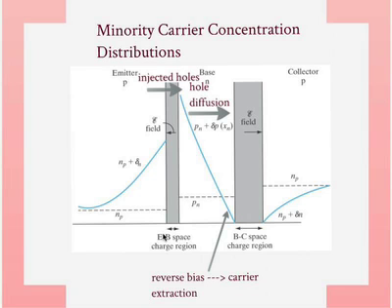Okay? Everything else is very simple. This side is essentially a forward biased PN junction. The electrons got injected across and they diffuse, and this is exactly what we solved before. As long as the emitter is large, it's exactly the same as before. On this side is carrier extraction, which is exactly what you had in your midterm. In this case, for electrons on the p-type collector.